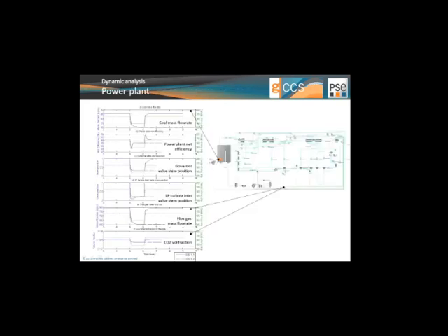Now, from the simulation results, starting with the power plant, what we can see is that at the beginning the coal mass flow rate will follow the disturbance that we have imposed on the system, but then it will take about half an hour to reach the steady state value for 75%. At the time where we switch again, it will follow relatively quickly, but again it will take about half an hour to settle back to steady state once we go up to full load.